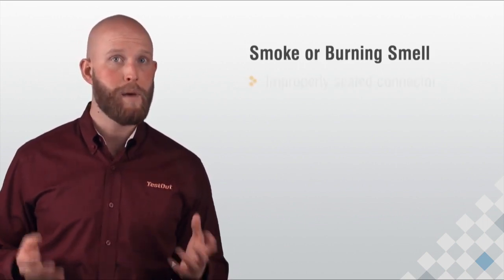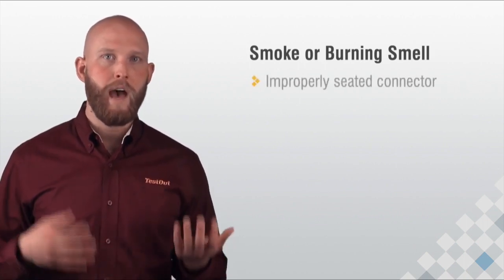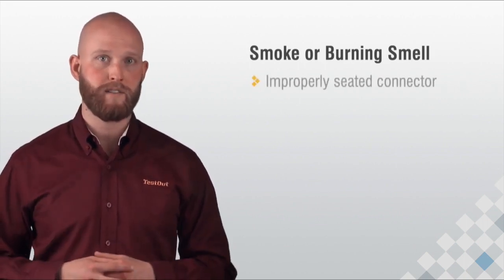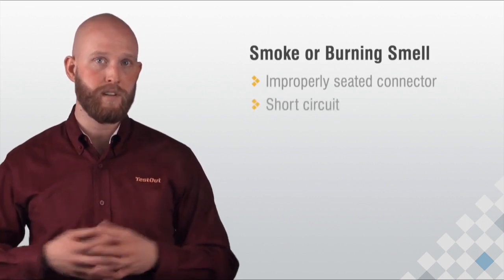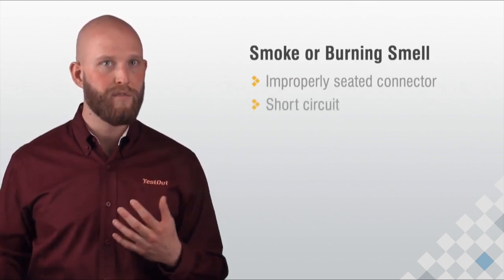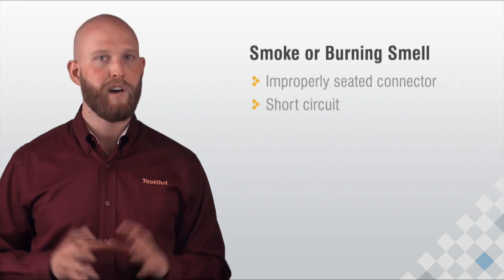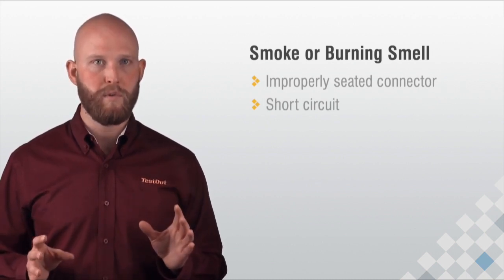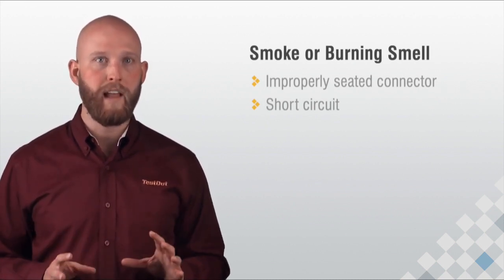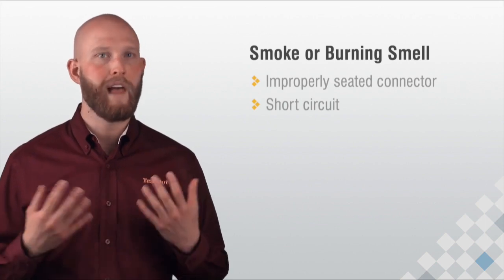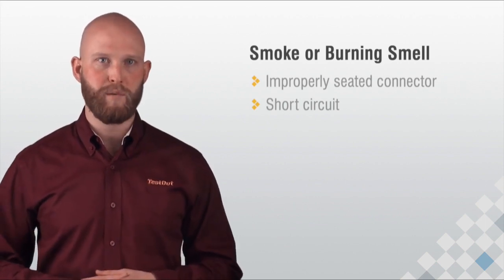It could be caused by a connector that isn't seated all the way and the electricity is arcing between the two ends. It could be caused by a short circuit in the printed circuit board of the motherboard itself or on an expansion board. Unfortunately, if you see or smell smoke, it's usually too late. It's unlikely that the components that were affected will ever work properly again and will need to be replaced.